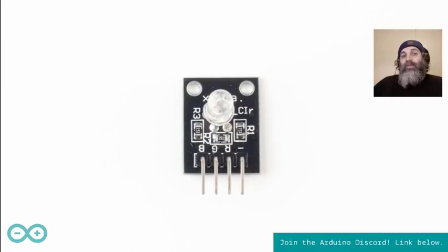Which means that if we basically have 3 lights, 1 red, 1 green, and 1 blue, we can compose any kind of light in the light spectrum by changing the intensity of each one of those lights. In this case, it's possible to integrate those 3 LEDs in a single housing, and what we see here is a very simple RGB LED that can be controlled with 3 pins independently. There are other technologies that make this easier in a way that allows you to add a lot more LEDs by daisy chaining them, but this is a very easy way to have a starting point to work with LEDs, where you control directly the intensity of light by changing the input to each one of these values.